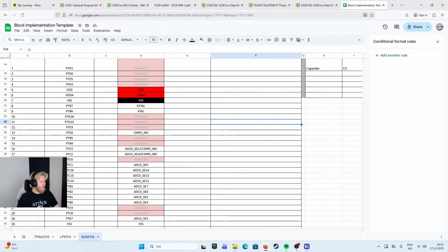Okay, so what is the alternative to this one? Or what is this really? Pinout. Oh, signal table. So we're at 13. So 13 is the one, or the next one that is not disabled. These can also be configured to be SPI, one of these or two of these. 10 and 11 can also be configured as SPI. So those two.